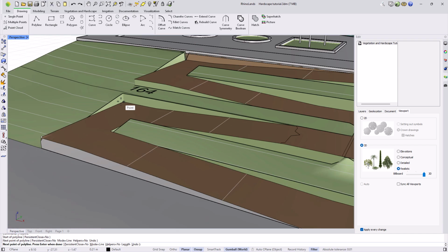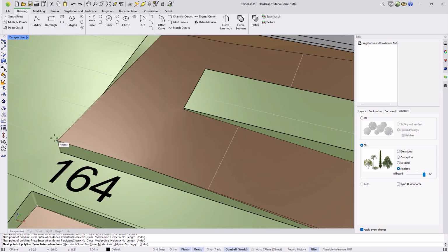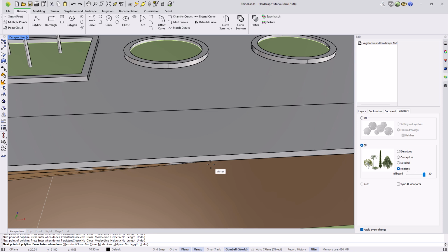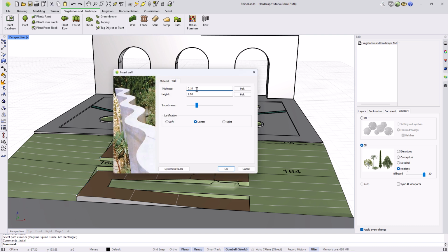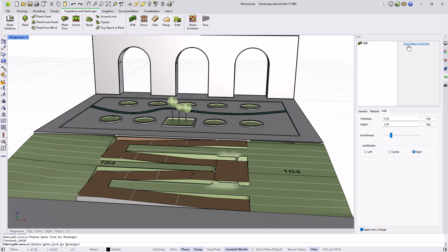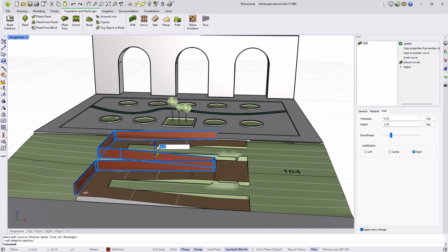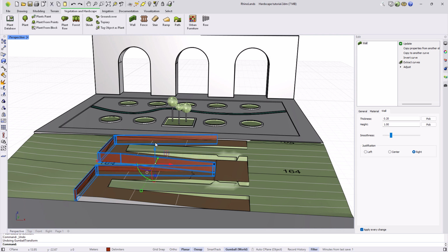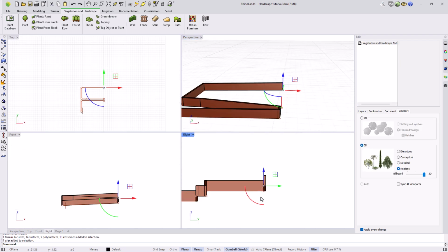Conversely, we can initially draw a line or polyline, like tracing the vertices created by the path. I move it 1 mm so that coplanar faces are not generated with the terrain, and I will create a wall again by selecting this curve, with a thickness of 0.2 and right aligned. We deactivate Snap to Terrain so that the curve fits perfectly and select it. To finish adjusting the position of its control points, I can isolate it in the view to select and align more comfortably.